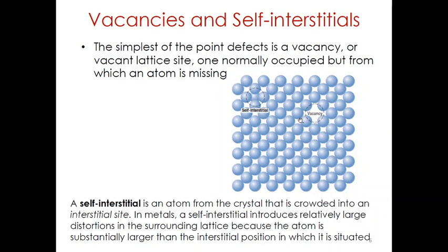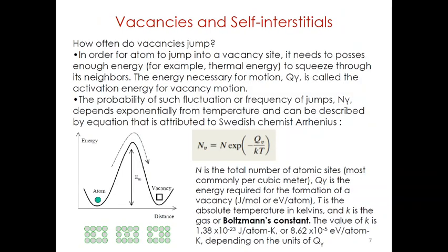The formation of this defect is not highly probable, and it exists in very small concentrations that are significantly lower in comparison with the vacancy. The necessity of the existence of vacancies is explained using principles of thermodynamics. In essence, the presence of vacancies increases the entropy, that is, the randomness of the crystal structure.